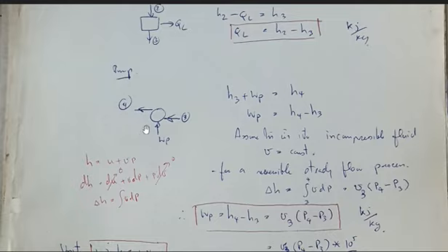So we will pump the water up to state 4. If we look at the formula, we get H3 coming in plus work of the pump also coming in equal to H4. So if we want to determine how much work we put into the pump, we get WP equal H4 minus H3.